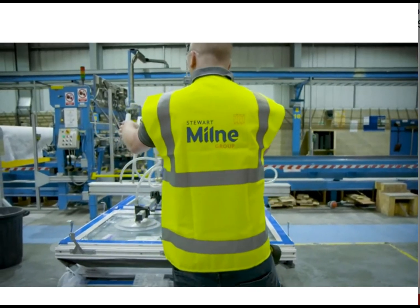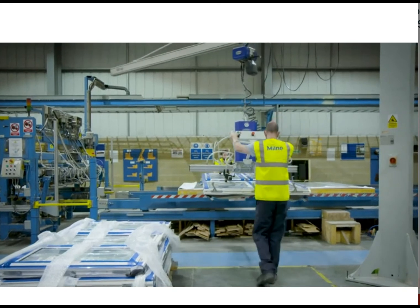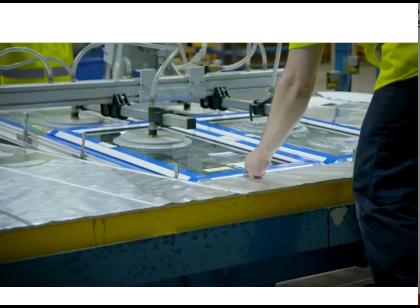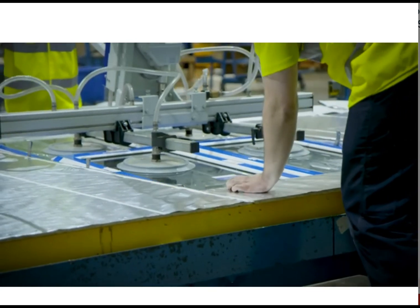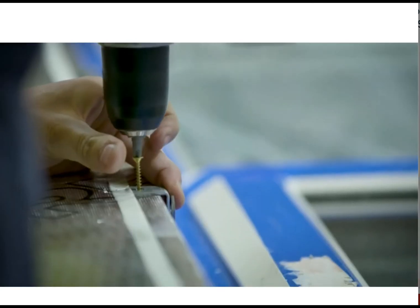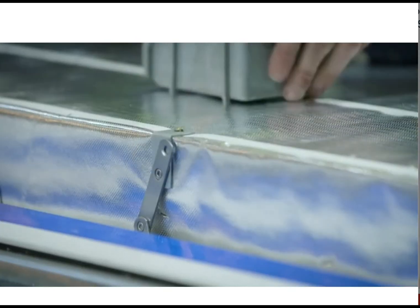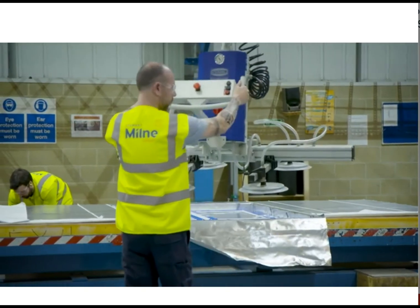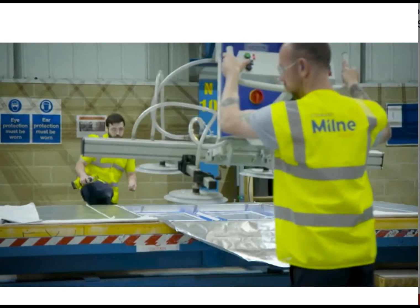UPVC windows and doors that have been supplied directly to the factory by the approved window supplier are fitted to the timber frame panels on sliding brackets. This means they can be transported within the depth of the panel and don't waste space. On site, they can be slid out easily into the correct position.